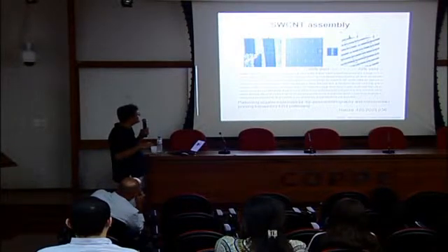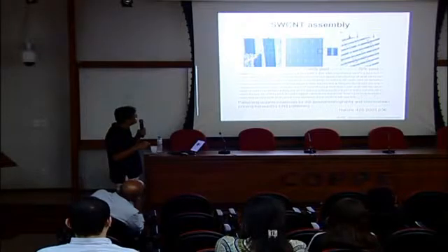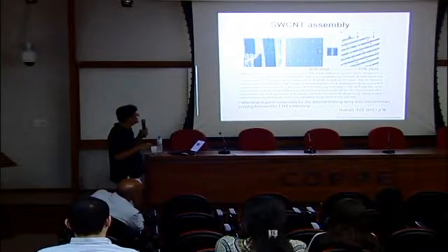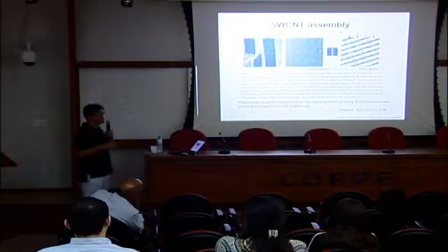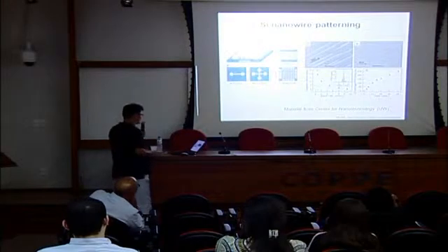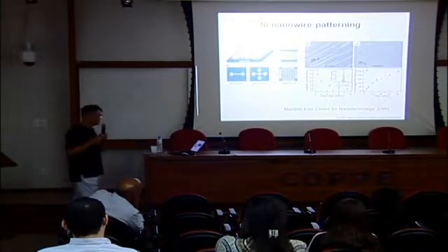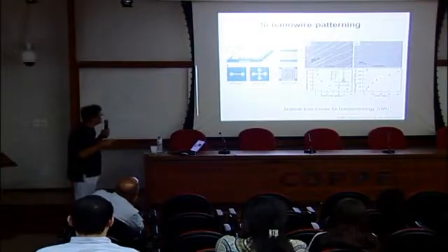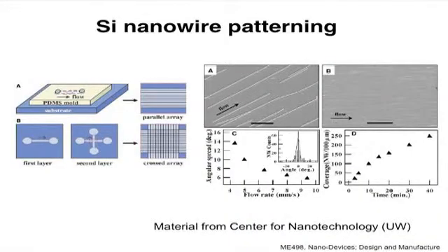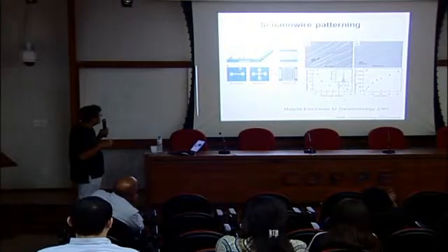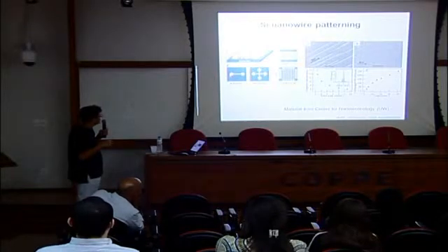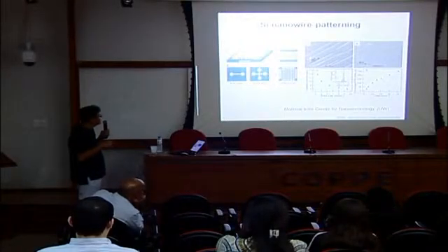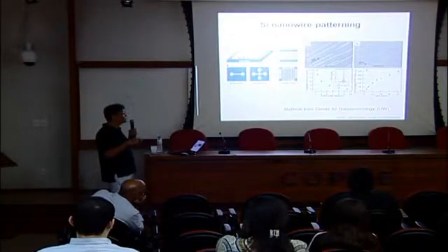So it was better. However, when it's coupled with electrodes, the yield was reduced. Okay, so some of the areas were kind of blank, or more than one nanotube was assembled onto that. Okay? So that's the self-assembly process. And in certain cases, in order to increase the probability, fluid flow was combined with the self-assembly process. If you see here, there is a microfluidic channel, and the surface was positively charged, and negatively charged silicon nanowires were transported through the channel. Due to the shear flow, they were aligned along the fluid flow in the channel.